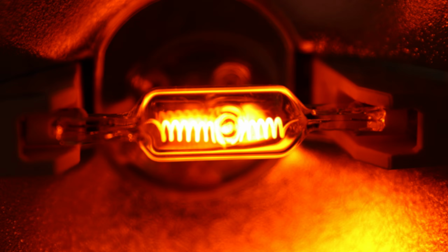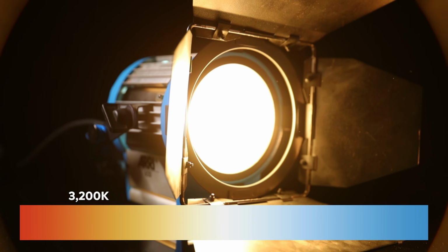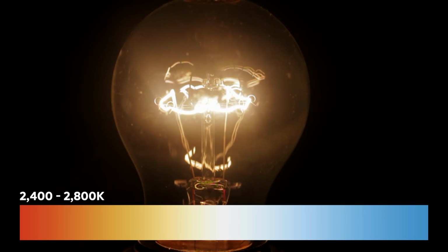All right, so how do they work? Well, tungsten globes consist of a tungsten filament, which is seated inside a quartz glass globe, which is also filled with pressurized halogen gas. This gas serves a couple of functions. The first is it increases the lifespan of the globe by recycling halogen back into the filament. It also allows the globe to operate at higher temperatures, thus increasing the output as well as increasing the color temperature. Tungsten lights have a color temperature of 3200 degrees Kelvin, compared to regular household incandescents, which have a color temperature of 2400 to 2800 degrees Kelvin.